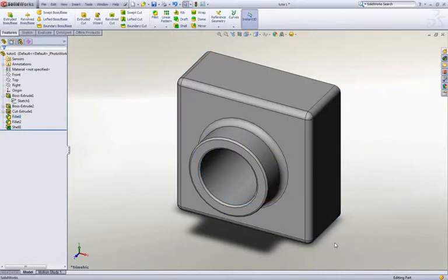To modify the radius of just the edge fillets, you need to remove all the fillets on this face and add them back as a separate fillet feature. This is required because all of the fillets were originally created as a single feature.